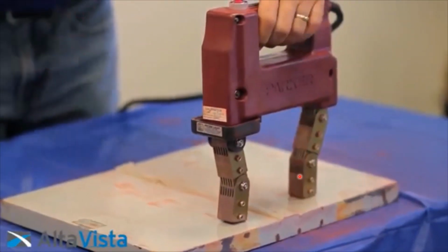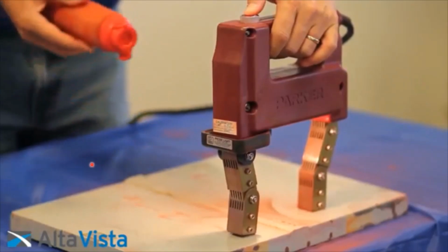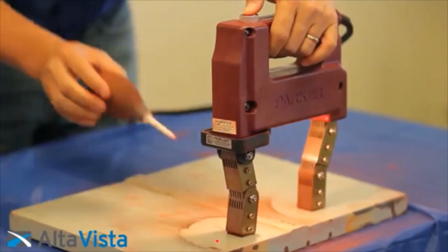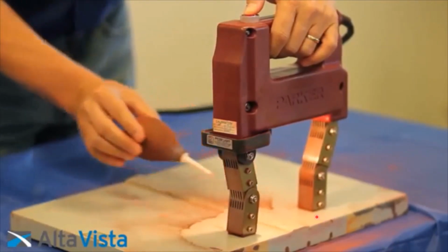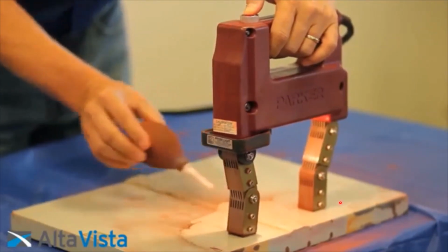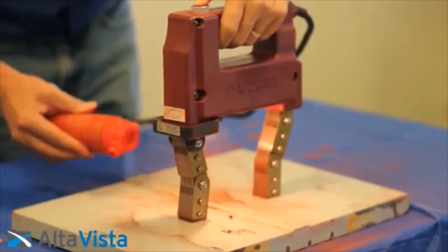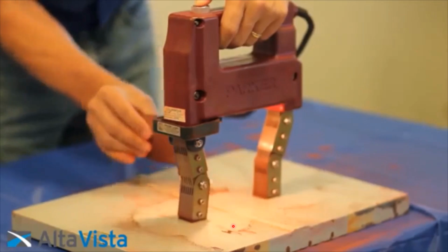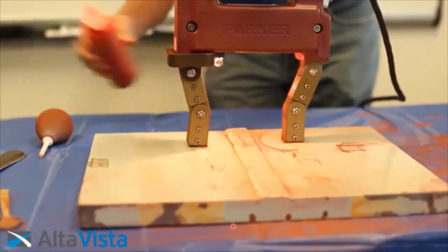During the process, the plates to be inspected are magnetized using a yoke. Iron oxide powders are gently placed over the area. The excess material is blown off. If there is any discontinuity, the iron filings will be attracted near the discontinuity. Now, if there is no discontinuity, we don't observe any iron filings in the same location.